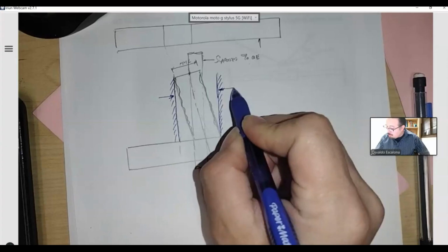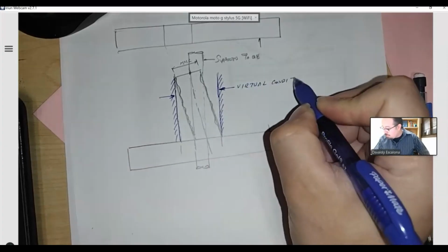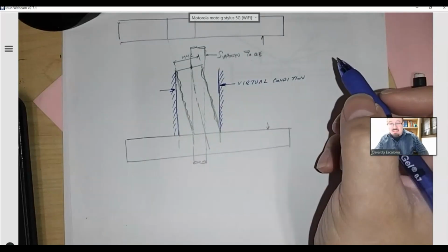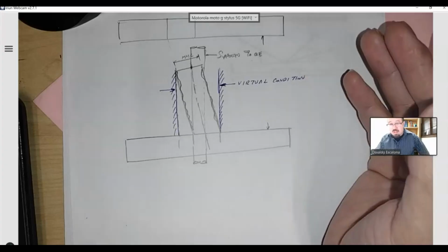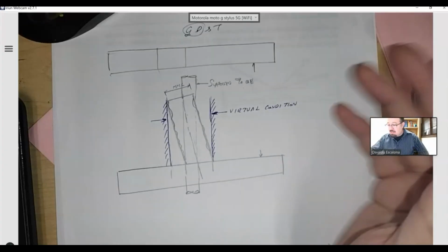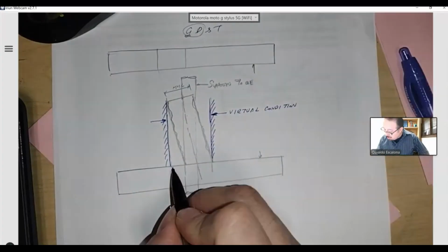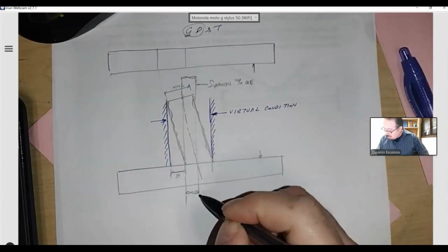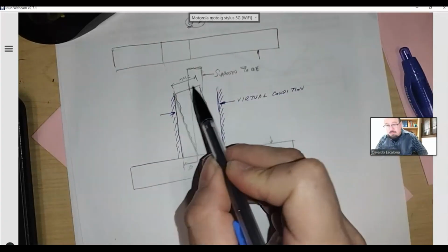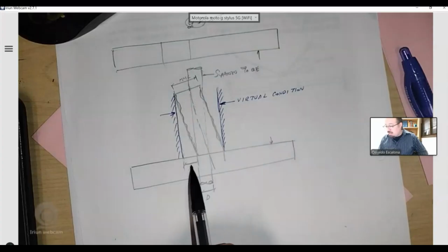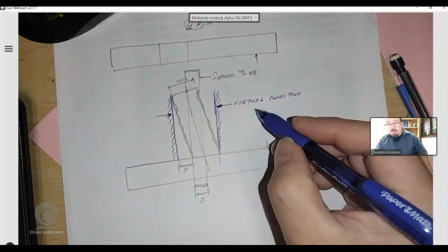size, is what we call virtual condition. And the virtual condition is the effect of me accounting for the worst case scenario in terms of feature size condition, the D, as well as the worst case scenario of geometric imperfection. So if you were to look at this little distance right here, that is the same distance that this one has, right? If I were to account for the maximum I can get and the crookedness I can get, I can have the virtual condition.